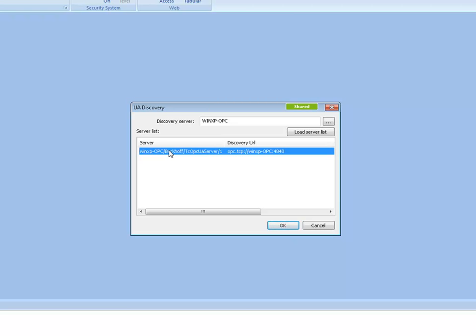We did not need to have DCOM, or, for the old timers, if you guys remember, the OPC Enum program, everything. No, what we have to do is to properly configure the server to have the discovery service available, so we can remotely connect to that server. I have other PCs here, like I was showing, the 162. Here it lists the servers that I have available there. That's simple enough, but when you're configuring a server, you can provide all the security that you want.